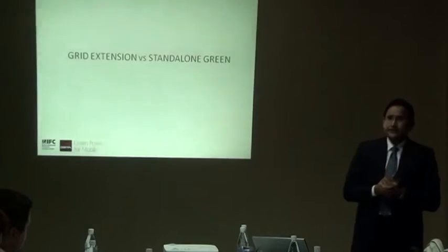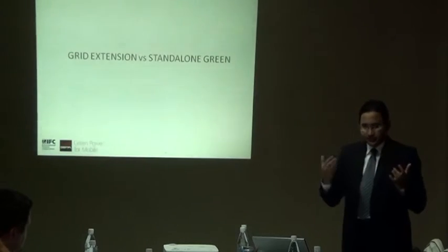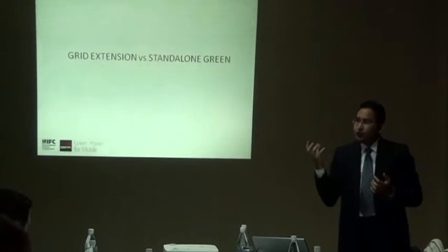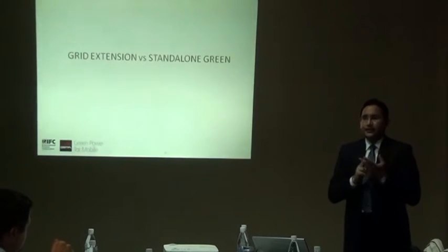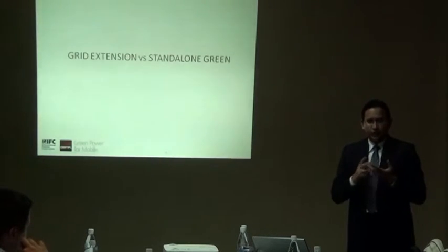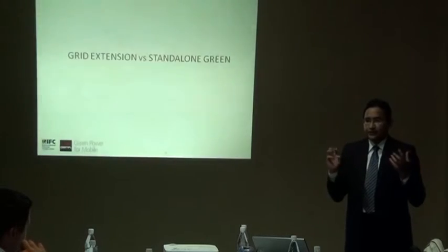Now the question is whether this grid extension is feasible, or whether standalone power generation is feasible. There are two elements to consider while doing this grid extension versus standalone analysis. Number one is, what is the availability of grid power? Let's say you are spending about $20,000 for extending the grid, but after extending the grid, what is the guarantee that you will have consistent maximum hours of grid availability?